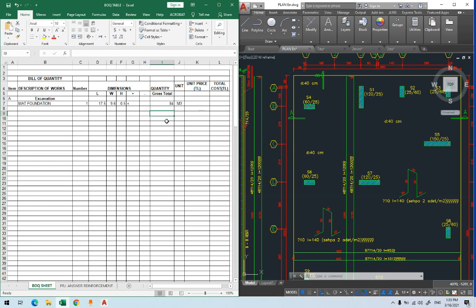You will understand this when we come to doors and walls, especially when we have a lot of windows inside. You will see which one will be easier to do. Some people will do it separately. They will start another section. They will say excavation minus. So this will be the things that will be taken out of the excavation. That's also totally possible. Whatever you prefer, it's up to you, but you have to know that if there is something to be taken out of it, you have to do the calculation. Now for this project, the excavation is 84 cubic meters.